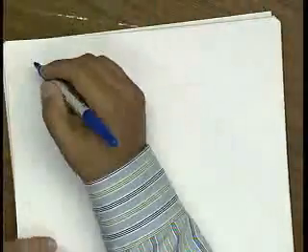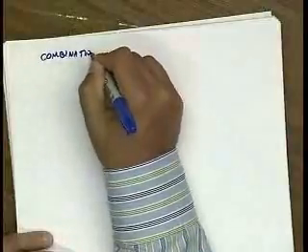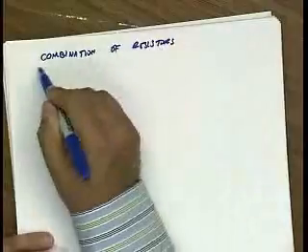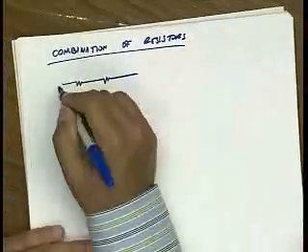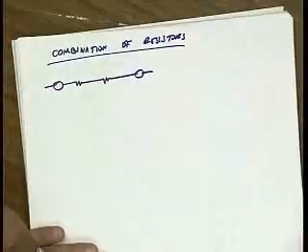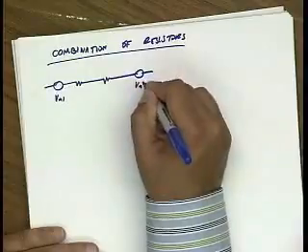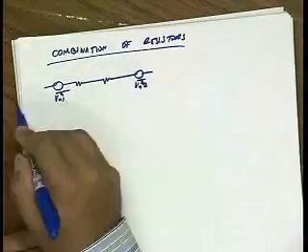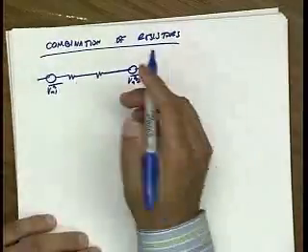All right, well, what about if we have more than one resistor? So let's say I have two resistors in series. Well, each one has its own voltage noise. I can put those in series, right? Say Vn1, Vn2. And so the total noise voltage across here, again, I say noise voltage, but you know what I'm talking about.